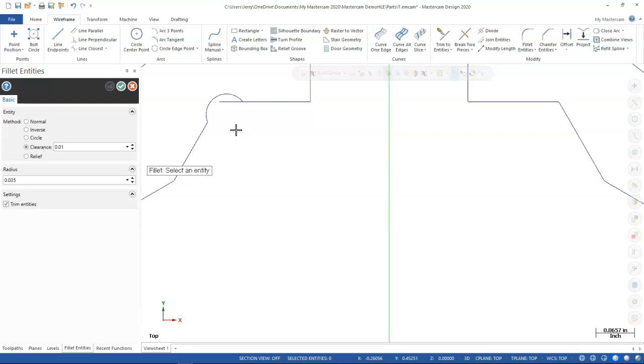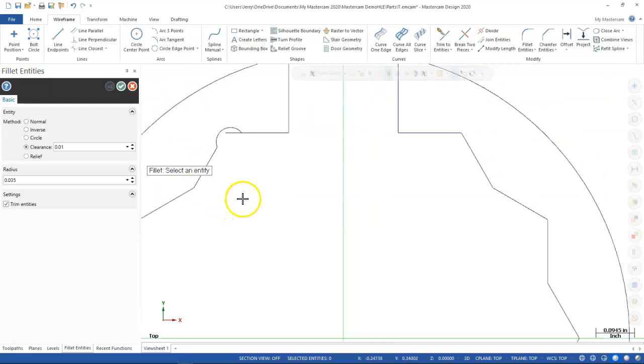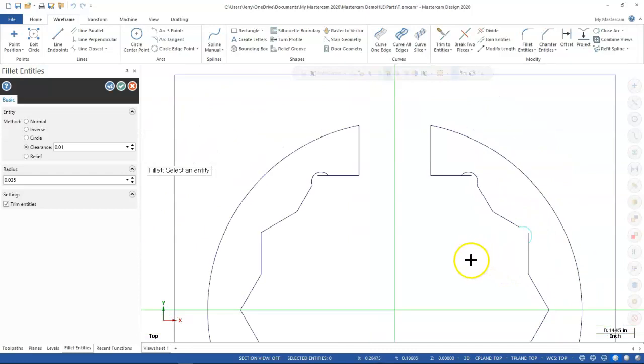But if I had an actual 1-inch sharp square, I would still be able to fit it in here, line to line, of course, because we didn't actually set up much in the way of clearance for the rest of the geometry. But on this point, I would have 10 thousandths before the sharp gets into that radius. Okay, so we're going to, I don't think we need clearance on those guys, but we should on those. So all of the exteriors,